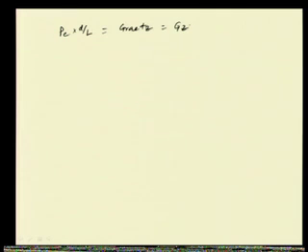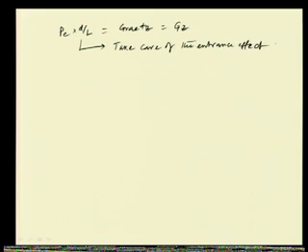So, this Graetz number is nothing but just some modification of the Peclet number, where D by L, that aspect ratio, is being taken care of to take care of the entrance effect. So, D by L is multiplied to take care of the entrance effect. So, this is called the Graetz number.